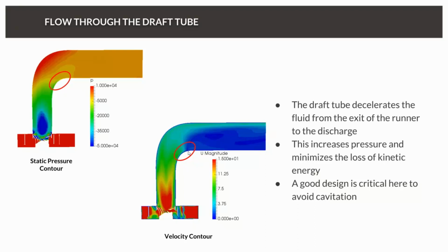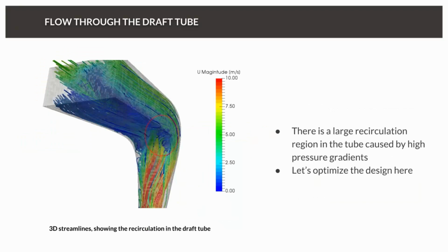On the right, this is even worse. You can see that the flow tends to the top and it recirculates at the bottom. And recirculation, again, isn't a great thing to have in any of these kinds of designs. And here's a nice way of visualizing that. This is what Darren showed before, but with a few more traces flowing through the model. I've highlighted one region of recirculation, but there are many in this design. And if we can reduce those and at least move them way downstream, then again we're going to optimize our design, improve the efficiency, and extract more energy from the flow.